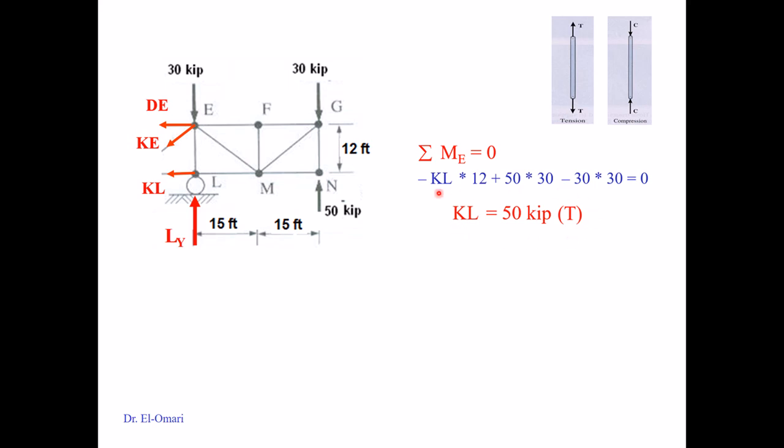Here's how you should write the answer, whether you write it with T or tension, but it's very important to write whether this is in tension or compression. Never learn that because it's positive, it's tension. No, you will see shortly that it could be also positive, but can be compression. So again, the steps: you get the answer positive, right assumption, then going out of the joint, tension.